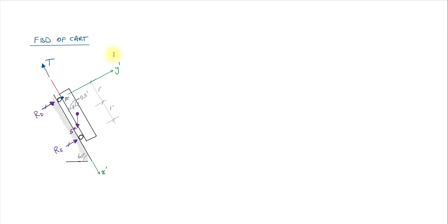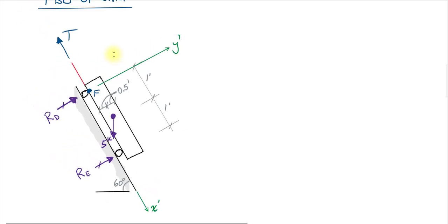Okay, so before I get started with that equation, I really need to be thinking about what that X prime component of the 5 kip load is. These things acting on a slope always get a little hard to mess with the angles. If we had this vertical line right here, and here's horizontal, our 60-degree angle is this one right here, isn't it?